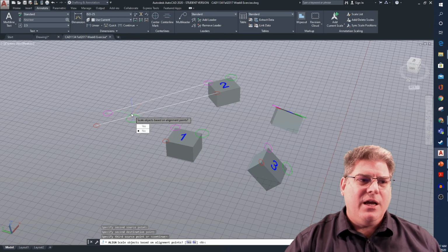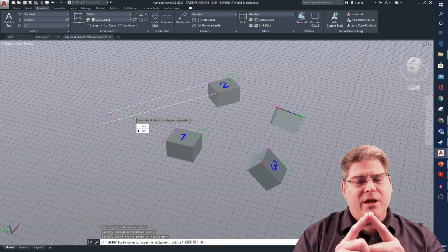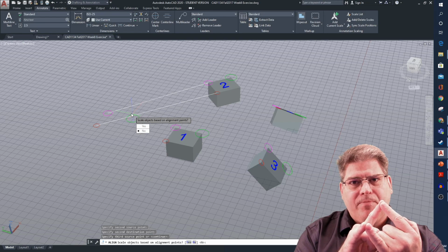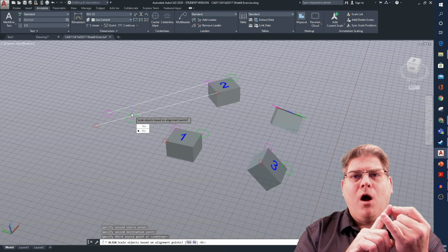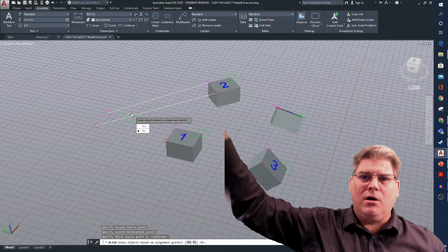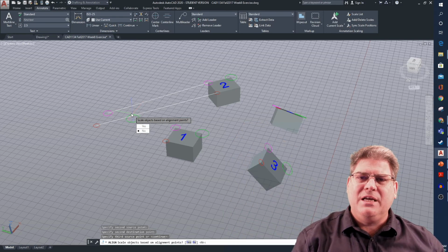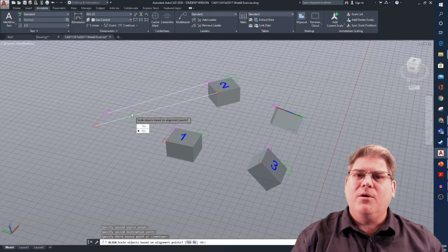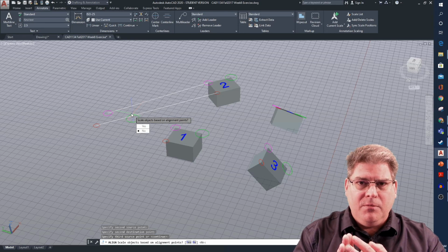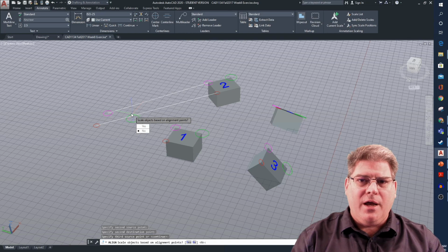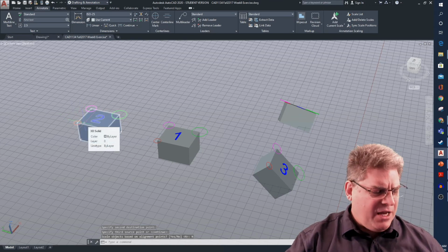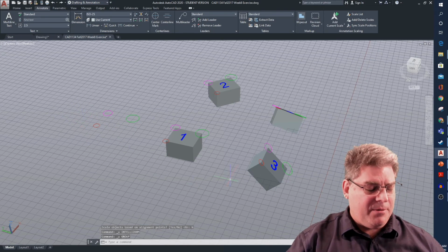And so the difference here is we've said I have a point, and then we're defining the second 2 points as either a line, okay, where it would scale it, or a ray. And the difference between a line and a ray is a ray goes infinitely long. And so by saying don't scale it, we're telling AutoCAD that this isn't a line, that we have a point and a ray. So it's going to align not just the point, but create an axis. Okay, so I'll say no. And so this time it does actually work out. It lines it up perfectly.